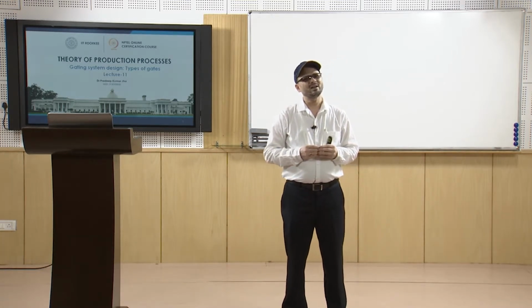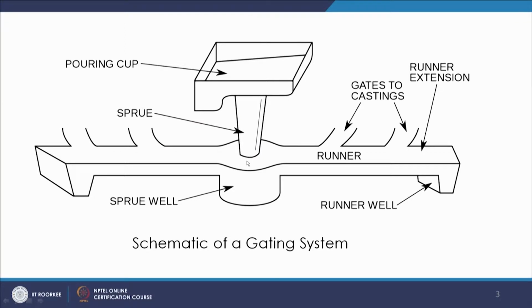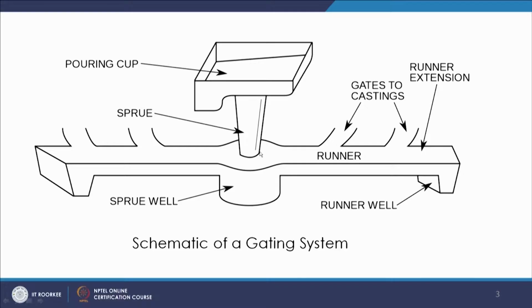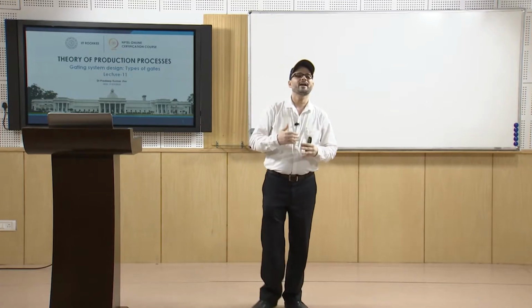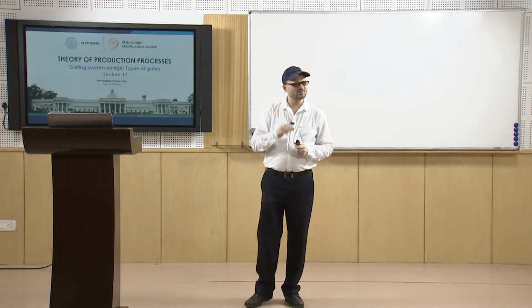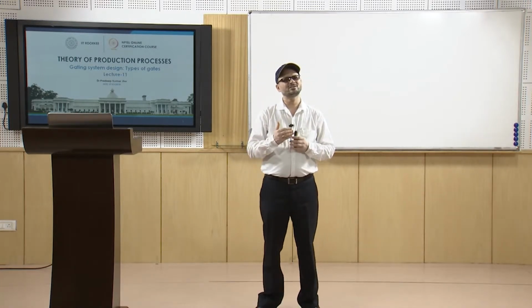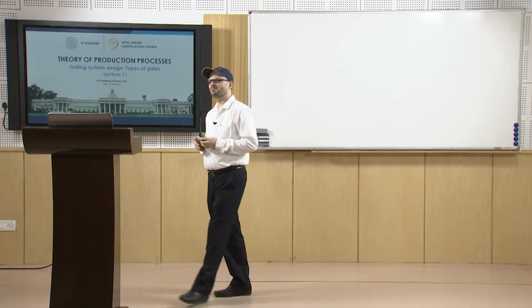In the pressurized gating system you will have this choke coming somewhere down the stream, not here, but in unpressurized. So in pressurized you will have the choke here. You ensure that this is all full, because once you have the minimum cross section here, you ensure that this whole section is completely full, and in the unpressurized case that may not be ensured. So you will have the minimum cross section here, and then the runner and the ingate dimensions depending upon their areas. The ratio of this choke area to the total runner area to the total ingate area is known as the gating ratio. That we will see later. So depending upon the position of the choke, you classify this as a pressurized or unpressurized gating system.